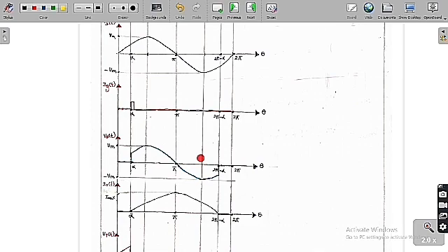So because of that, the current is now going to decay, because negative voltage is applied. So the current is going to slightly decrease from pi to 2 pi minus alpha. Therefore, in that region, as the thyristor is on, the output voltage is equal to the source voltage also. So it is also the same thing.